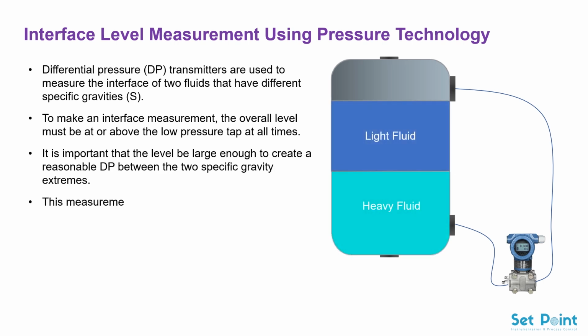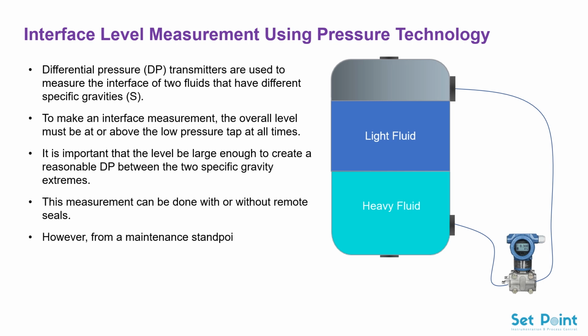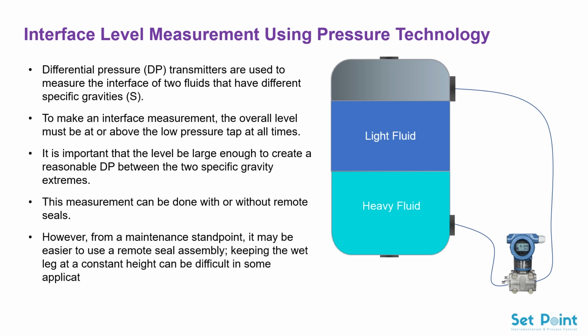This measurement can be done with or without remote seals. However, from a maintenance standpoint, it may be easier to use a remote seal assembly. Keeping the wet leg at a constant height can be difficult in some applications.